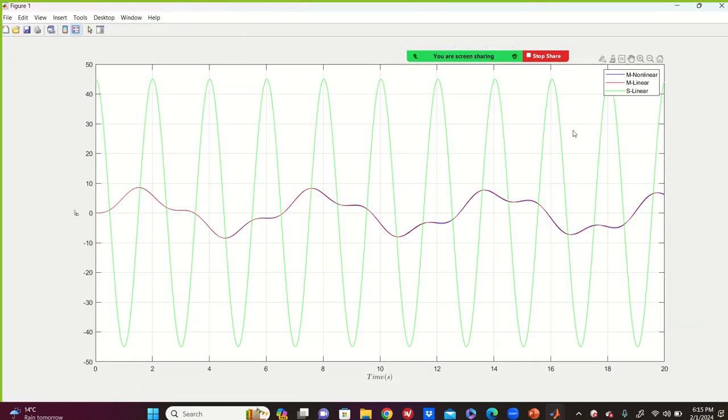See the difference between the stationary linear pendulum, purely sine solution as we derived by hand, and it's a marginally stable system because the two roots or poles are on the imaginary axis, as I explained in the previous class. But you see that for the linear moving pendulum it's not completely sine, but it's a harmonic. Do you see that? That's the difference between them. So the disturbance here affects the system a lot. The disturbance is that sine of t. You got it? Everybody? Yes?